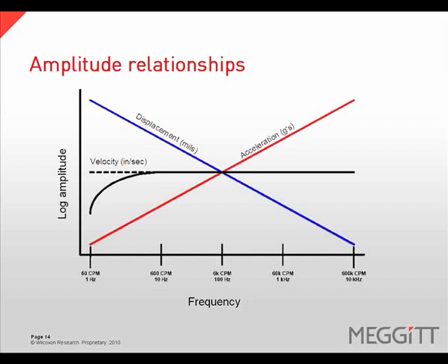Vibration can be measured in acceleration, velocity, or displacement. While each has its own merits, the same vibration data can seem very different. Displacement accentuates lower frequency events and is often used for things like balancing when we are only interested in rotational speed. Acceleration accentuates the higher frequency events and is commonly used to provide early detection of bearing problems and lubrication-related problems. Velocity is the most commonly used and is a good balance when looking at most frequencies except at the upper and lower frequency extremes.